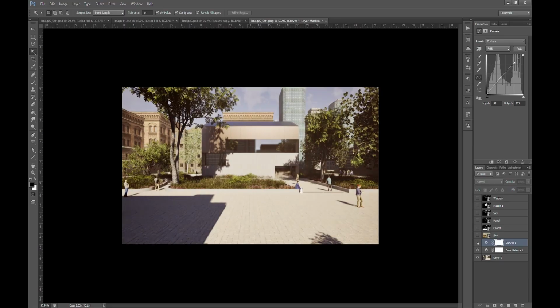You see the difference? The same thing with color balance. That was before. So you see, it was kind of very blue, but remember I had the fog. Remember how I had the fog in the Twinmotion setting? That's on purpose because I wanted to have this kind of textured look in the actual air. So that's the fog, and that's why it has this hazy blueness. It's hazy cool, and you see how this is much warmer now, right? So that's what the color balance does.